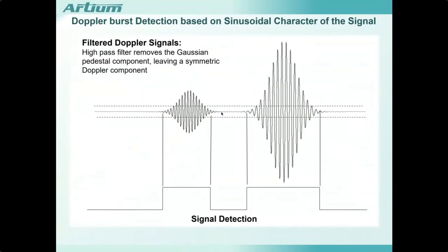These signals arrive randomly because the particles are essentially Poisson distributed, so the signals will similarly arrive in a random fashion, and they'll have a whole range of sizes. And the objective is to detect when there's a signal there, and send that information over to the processing means to determine the frequency of the signals.